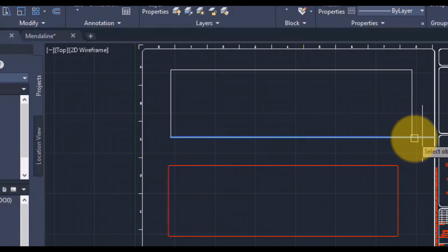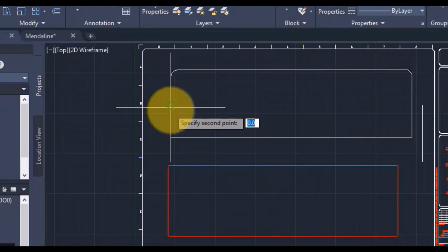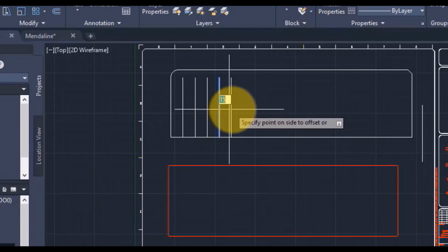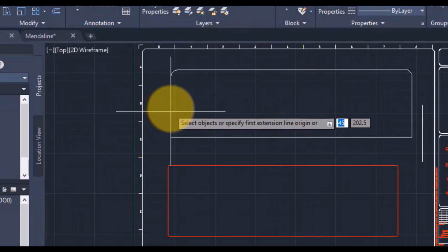You're basically corrupting the integrity of your own circuit. So the Suntech tutorial suggests using ATrim. Yes, ATrim, AutoCAD Electrical Trim. It's smart. It knows that if you trim a wire back, it also needs to clean up the connection dot that's no longer needed. It keeps the drawing and the database in sync. And for moving things, there's this command called scoot. I have to say, it's a great name.